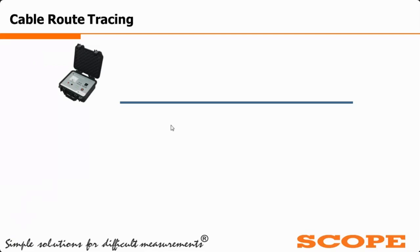So Scope is offering the CFL AG2, which is a 20 watt powerful audio generator, which is connected between one of the cores, which is continuous towards the end. This core is earthed at both ends, and the return path of this audio generator is connected to the earth. This audio generator is injecting a sinusoidal signal with a very high frequency in kilohertz. These signals are injected into the cable, and the path is completed through the earth.